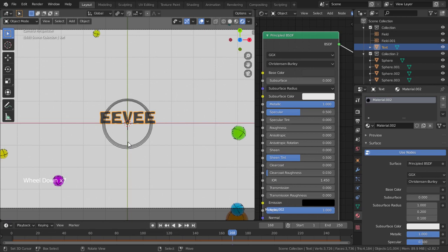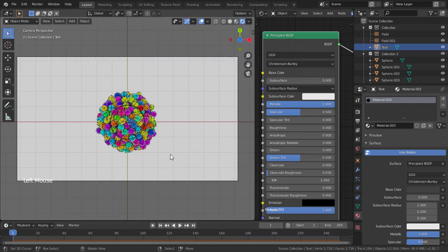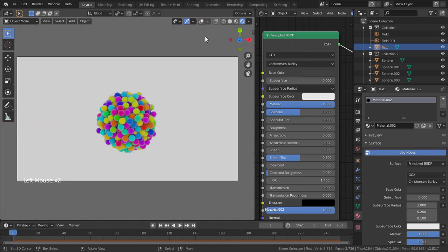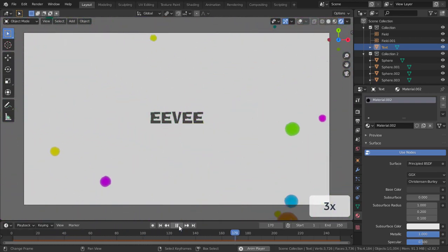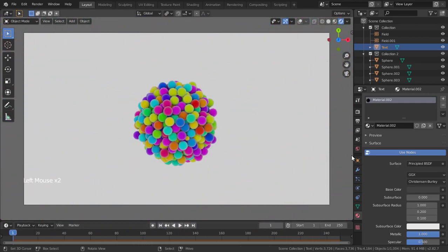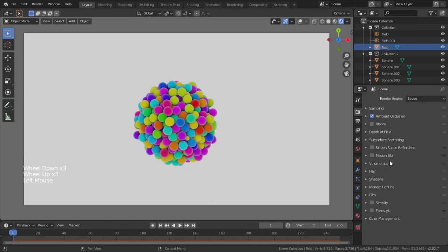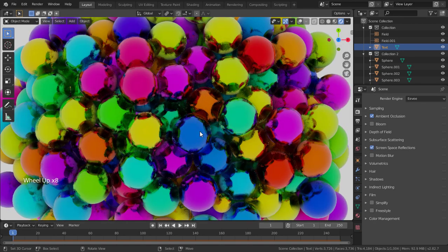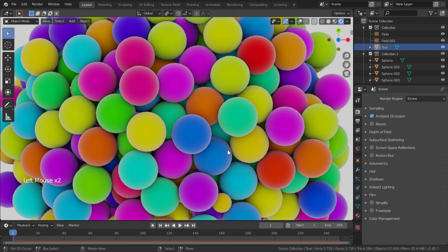Now go to the start frame in your timeline, and click the Show Overlays. And close the shader editor. Now you can see the created materials are blending light perfectly. For this animation we don't use the screen space reflection, because it gives a noisy reflection for this scene. So, we didn't use that render feature for this scene.